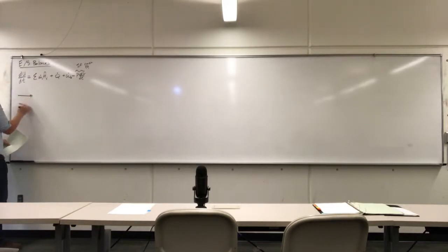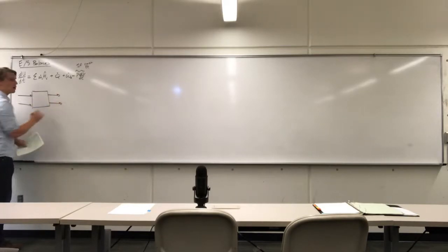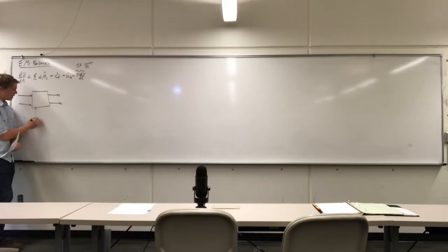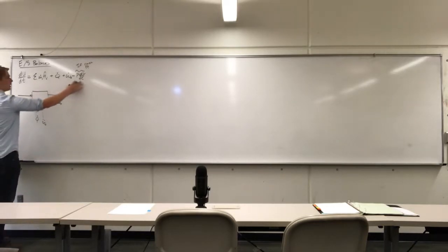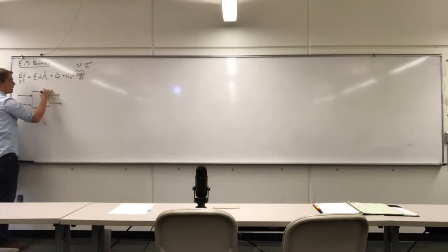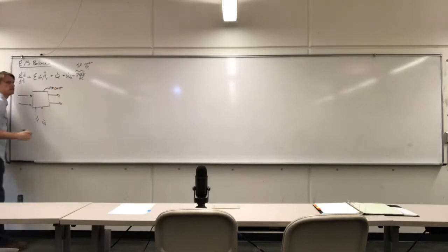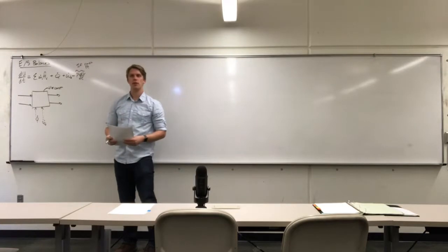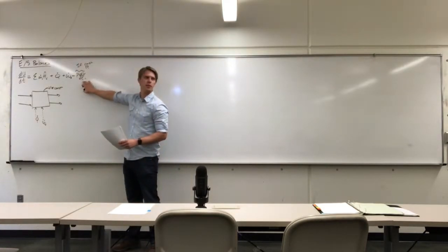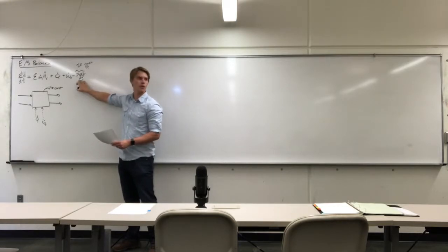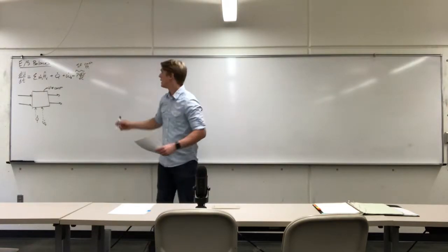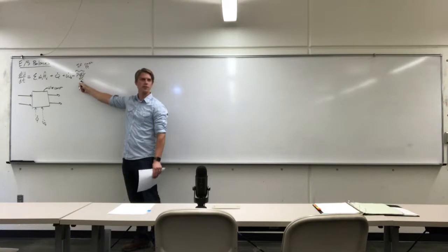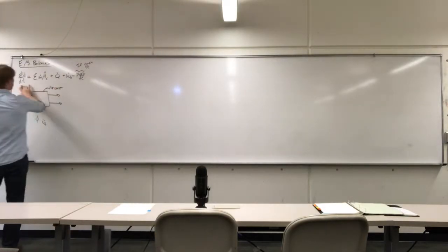So generally, what that means is we can have an arbitrary number of streams coming in or out of a process. The way that this has been drawn, we have heat entering, we have shaft work entering, so positive work is going into the system. But again, this is a convention that can be changed quite readily. And then lastly, due to this PdV term, this is a work term as well, that means that here the volume is not constant. This is something that we'll see most often when we do the generalized piston cylinder type devices, but in a real process you obviously want to avoid the system expanding and contracting. Maybe for a benchtop scale thing you can pop a balloon on it so that it could expand and contract. But in a very, very large scale process where you're processing millions of tons of material, it's best to have rigid walls.